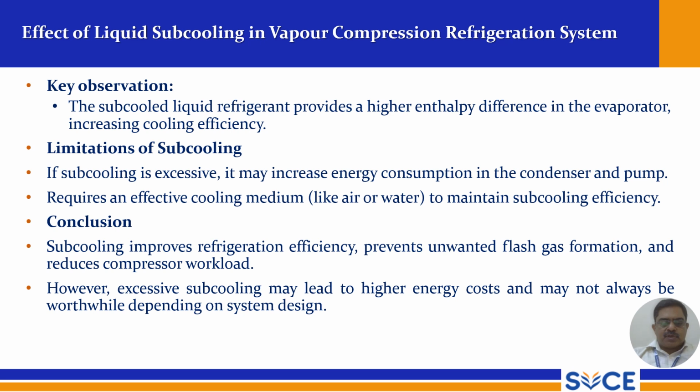However, excessive subcooling may lead to higher energy costs and may not be worthwhile. Excessive subcooling is not worth it, depending on system design. It should be optimum, and only that optimum subcooling should be applied here. More than that is not desirable. It gives unwanted load to the compressor and other accessories, the condenser and pump. So that should be avoided.